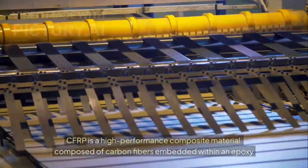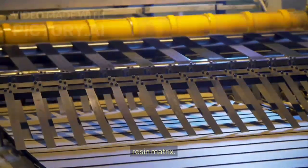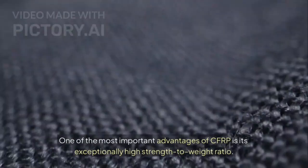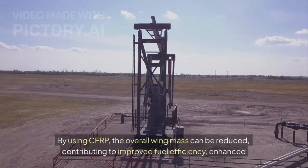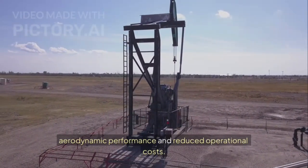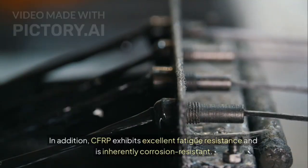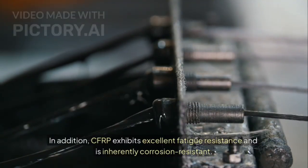CFRP is a high-performance composite material composed of carbon fibers embedded within an epoxy resin matrix. One of the most important advantages of CFRP is its exceptionally high strength-to-weight ratio. By using CFRP, the overall wing mass can be reduced, contributing to improved fuel efficiency, enhanced aerodynamic performance and reduced operational costs. In addition, CFRP exhibits excellent fatigue resistance and is inherently corrosion resistant.